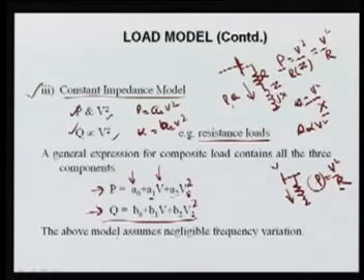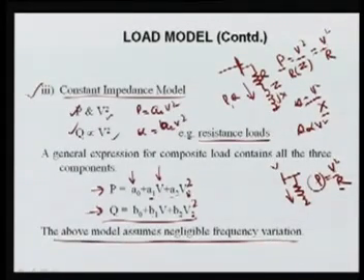So this model assumes negligible frequency variation. So in this load model, we have not taken into account the frequency change of the system. It is only the voltage. So it is not taking the dynamics of the variation of even the voltages. It is only again these static equations that we have taken, and depending on the various loads we have formulated this.